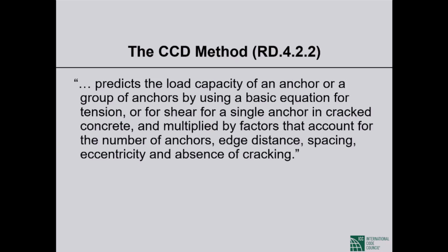So once again, this is very, very important. The concrete capacity design method predicts the load capacity of an anchor or a group of anchors by using a basic equation for tension and a basic equation for shear. Each equation is for a single anchor in cracked concrete, which is multiplied by factors that account for the number of anchors, edge distance, spacing, eccentricity, and absence of cracking.